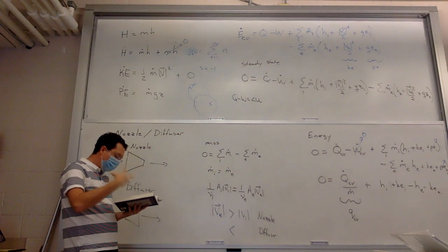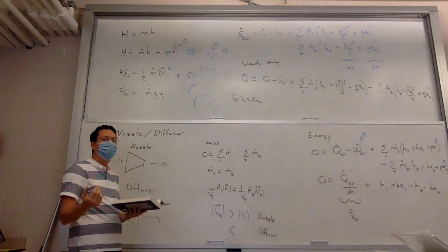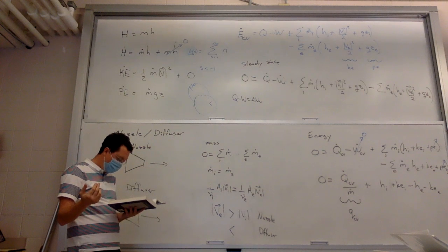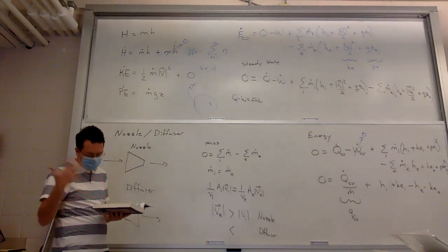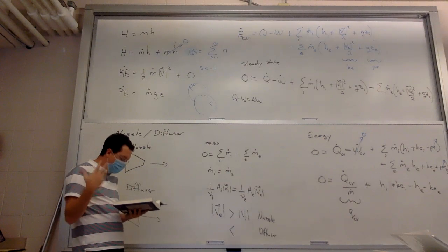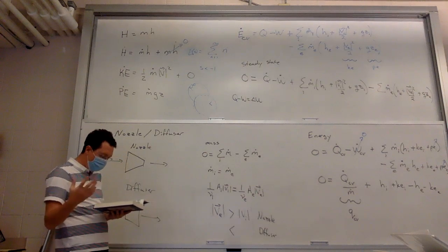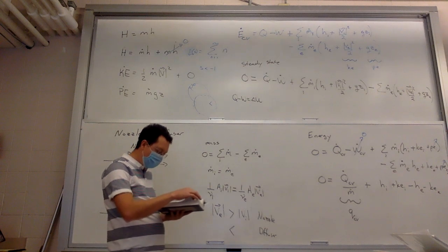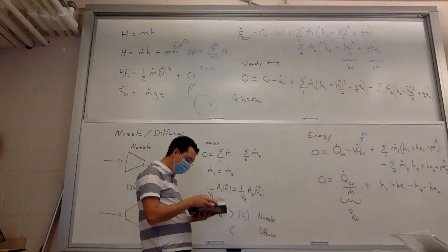The steam goes through the nozzle. There's negligible heat transfer. What does that tell you? You can assume Q is zero. Yeah. And no significant change in potential energy. Well, that's always going to be. At the exit, you're going to be given a pressure and a velocity, and you know the mass flow rate.